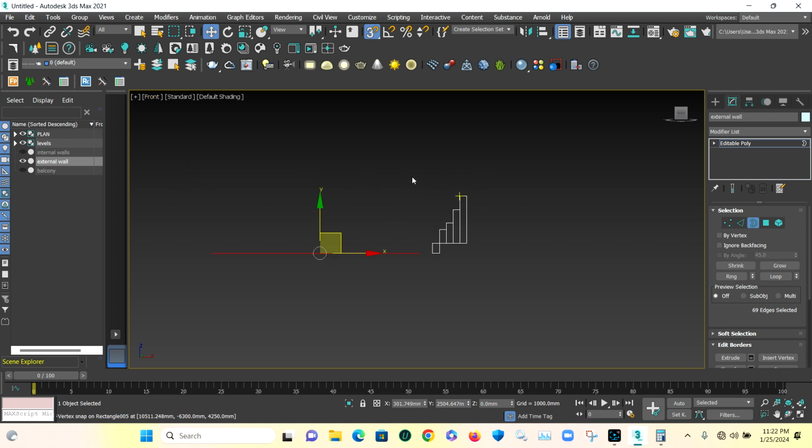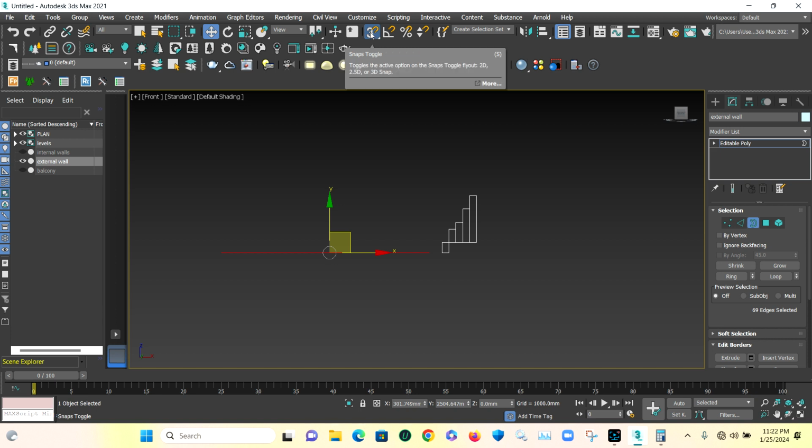Now once you get to front view, please be careful here, don't make any mistake. Once you get to front view, you want to build this wall, how do you do it? Hold shift on your keyboard. Now put your mouse at Y, because we are building in the horizontal direction. Now left click and hold, then drag. Make sure snap is on and vertex is on inside that snap. Now I repeat, hold shift.